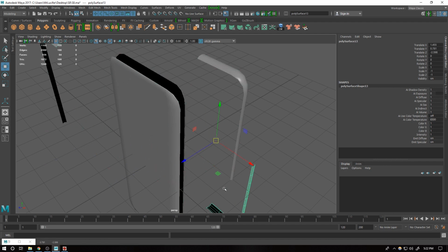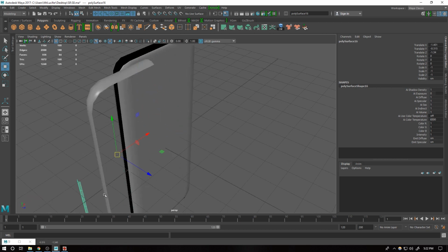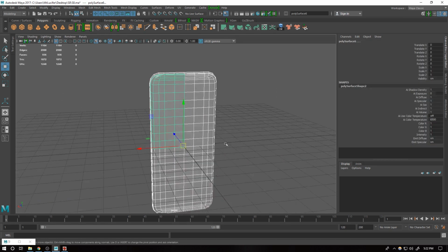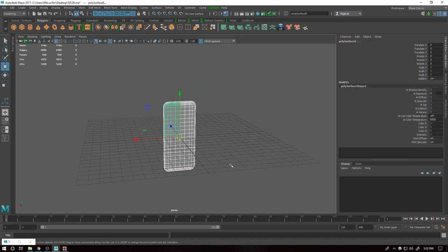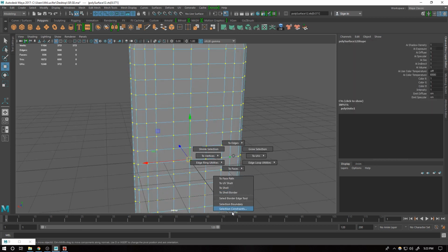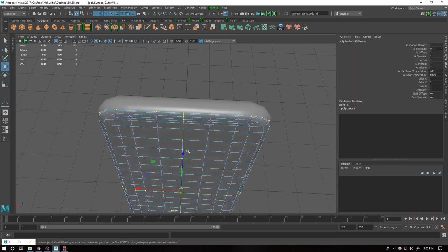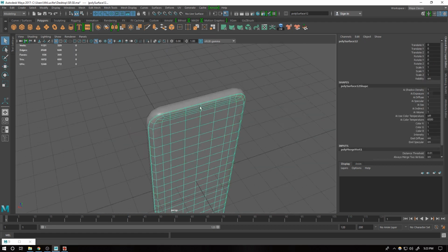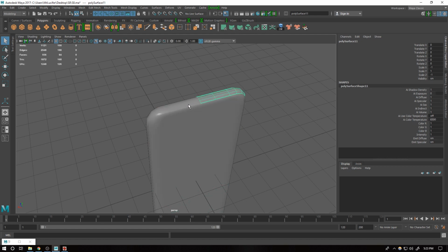This cross checking, maybe this mesh is going to duplicate. Okay, so now I'm going to merge all this, but I'm going to merge it one by one, because otherwise this vertex is snapped to this object, and if I select the whole object it will merge to this object, so I don't want that.